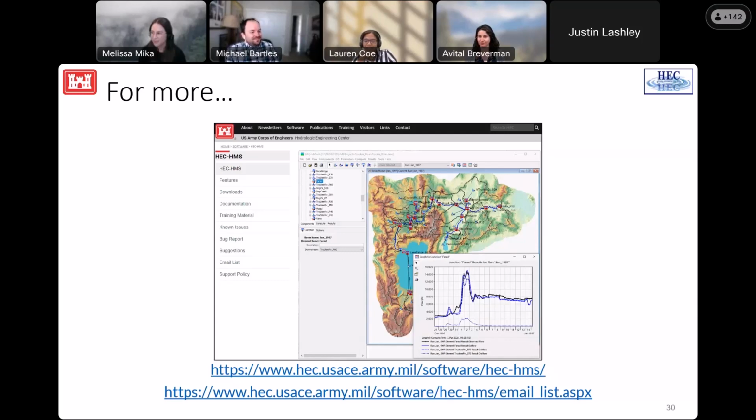Yeah, I've definitely used it to do something like the example you were mentioning. If there's been changes in the watershed, the best way to take out those non-stationarities, I guess, or changes in the watershed, was using an HMS model to boost our peak flow frequency estimates.